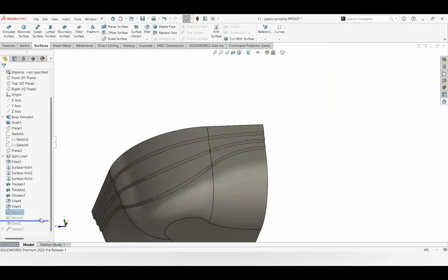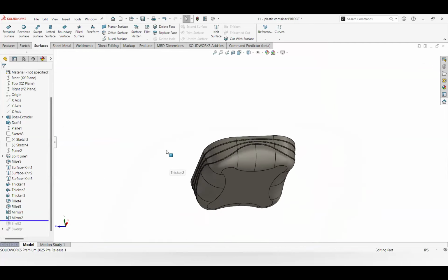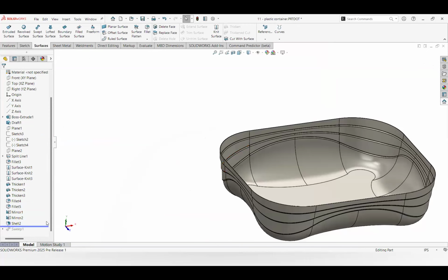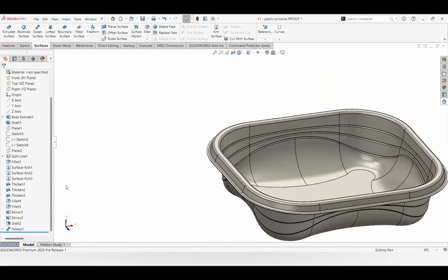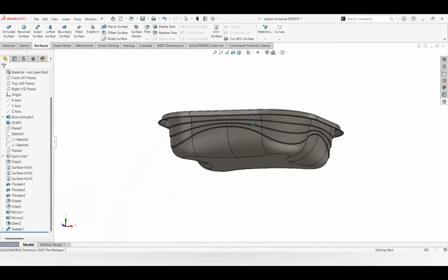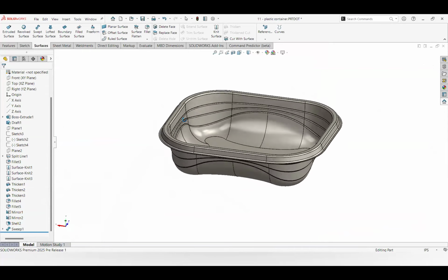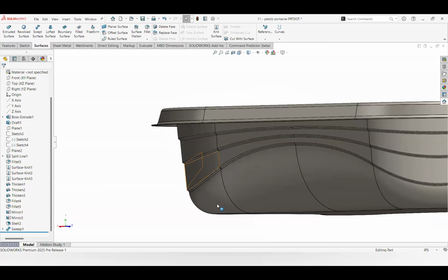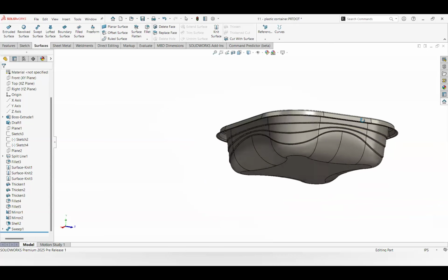Okay. A couple mirror operations to then get the whole shape. Shell, easy enough just to make that thin, and then swept brim around the outside. So, you know, if somebody presented this to you and said, we need you to model this, hopefully some of those ideas help, like when you see stepped walls, if they're uniform to the shape, see if you can use a surface thicken rather than having to try to sweep your own surfaces around all that stuff. That would have been really painful.